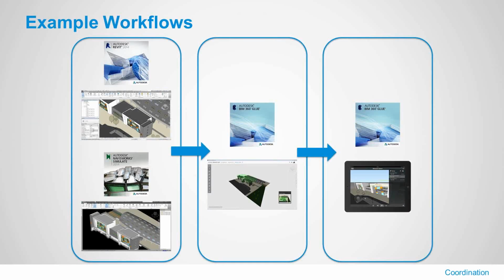I also want to talk about BIM 360 Glue here as well, because you can publish your data directly from Revit, or you can publish the data directly from Navisworks. You can get the add-in here and publish it directly to the cloud. With Revit, you can publish it as separate models, and then you can merge them together on the cloud, or with Navisworks, you can merge them all together and then publish them to the cloud as one merged model. What's interesting with Navisworks is it holds all the material data as well, so when you're up there on the cloud, you can actually see all the material textures transfer through.